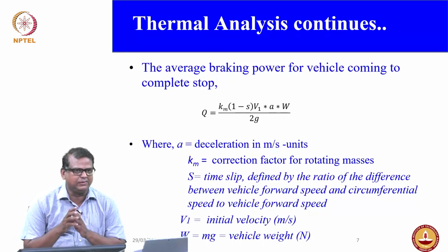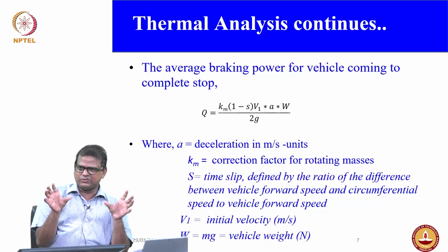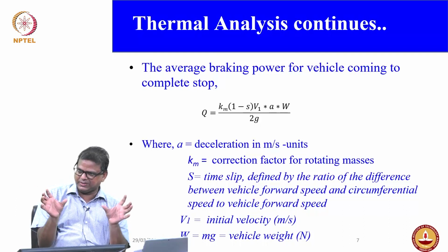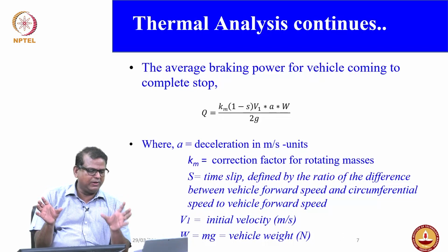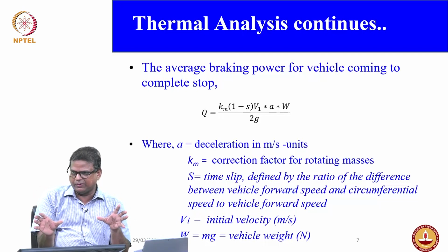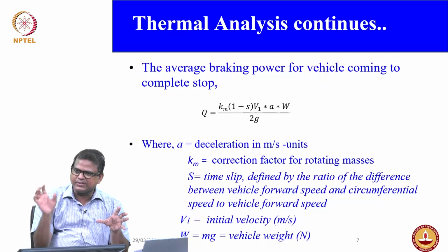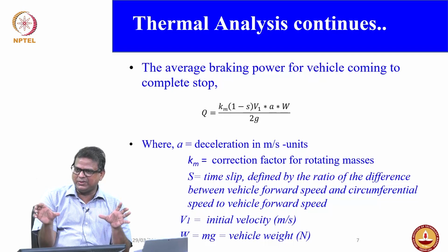There are two things here. Assuming that you have 2 gears, whatever speed is given by the input, if they are the same size, you would expect the same speed. So if I give 100 RPM to my input gear, the output gear should also give 100 RPM. Instead, if it gives 96 RPM, what do you think? It's reducing the speed. So there is a slip.